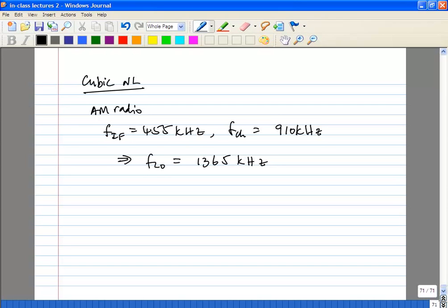Okay, so assume you don't even have an interferer, you only have your RF signal at your input. Your RF cubic term would generate a 2 omega RF minus omega LO term.